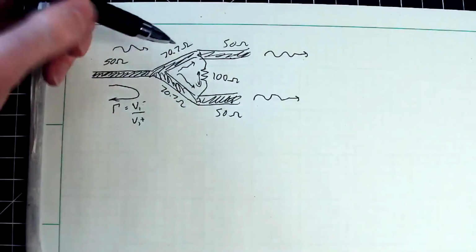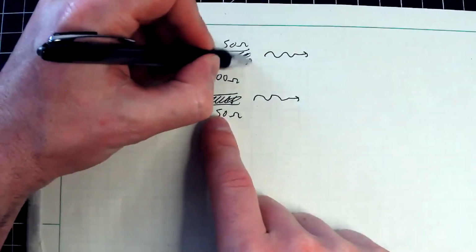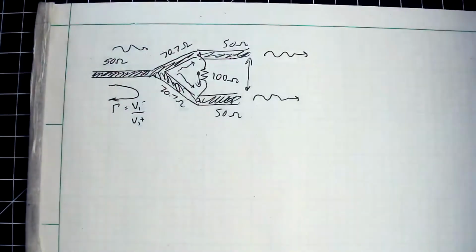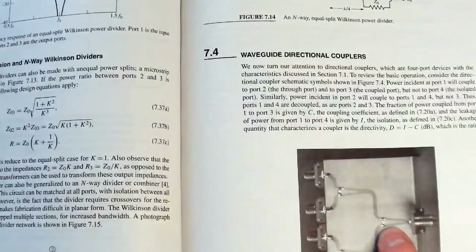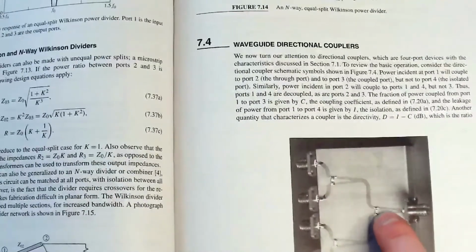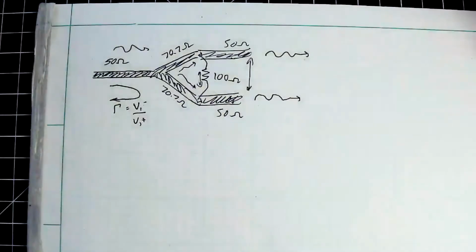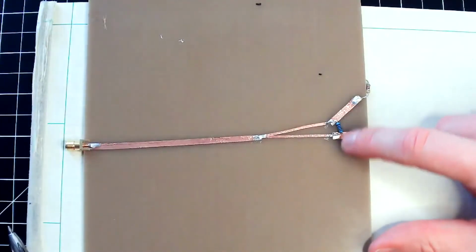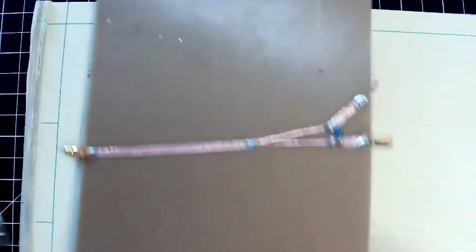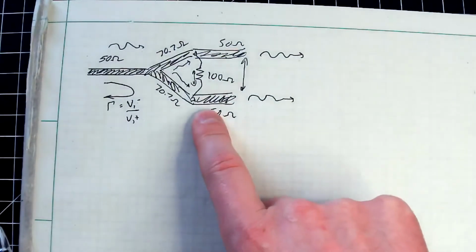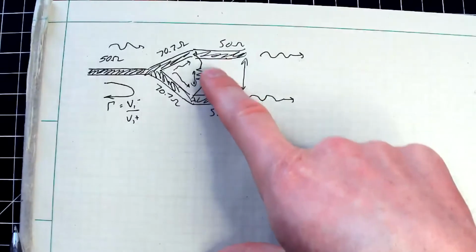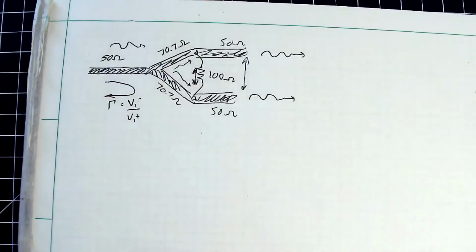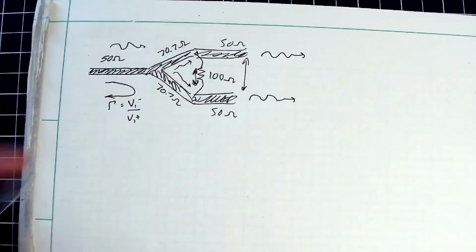An interesting question, though, is does the physical length from here to here have an effect on the impedance of my divider? Because they're using this tiny little chip, ideally it seems you don't want any sort of phase delay looking down in there. Otherwise, that'll affect your divider's performance. So I'm curious, does the physical length here introduce phase issues that mess with that as well? In an ideal Wilkinson divider, there is no electrical delay looking up and down here, so I'm curious if that needs to be compensated for in a real device.